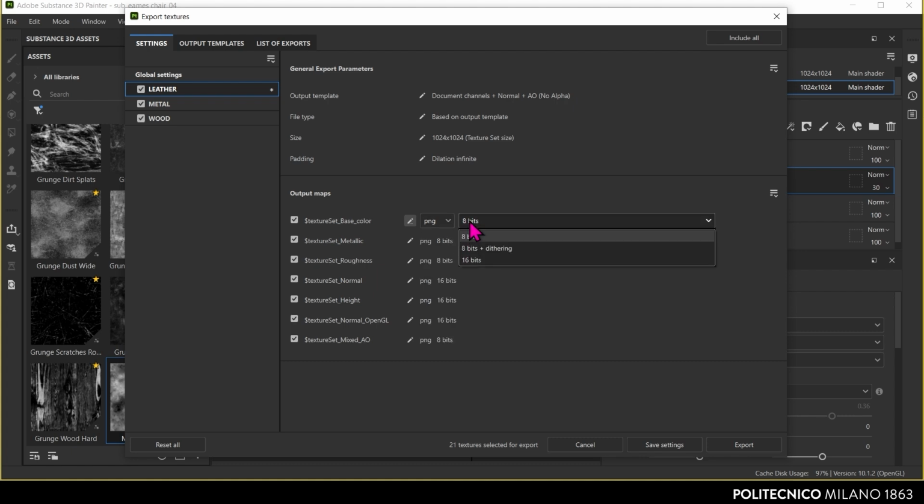Additionally, we can customize the resolution and bit depth, bits per channel, to ensure the textures meet the desired quality and performance standards. For instance, we typically use 8-bit textures for general workflows, while 16-bit and 32-bit textures are preferable when we need higher detail or greater color depth, especially in complex materials like HDR environments or detailed bump maps.